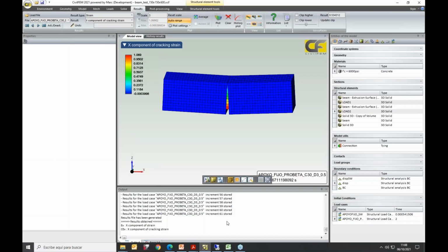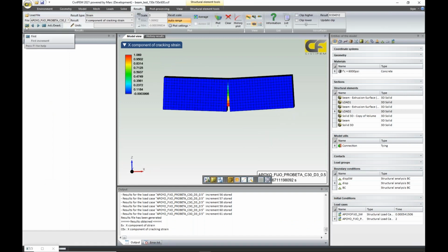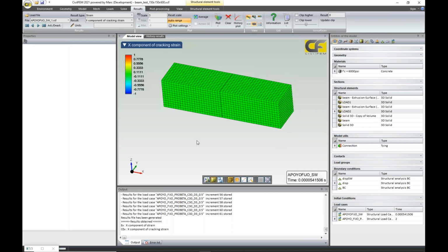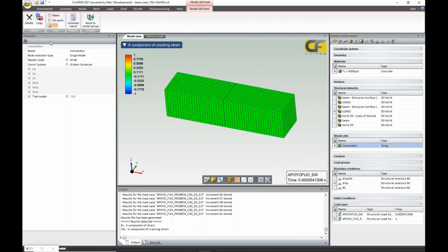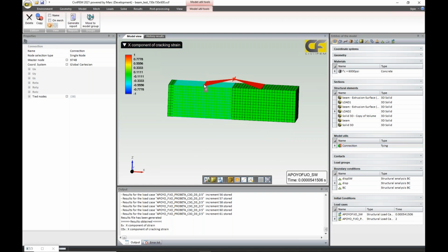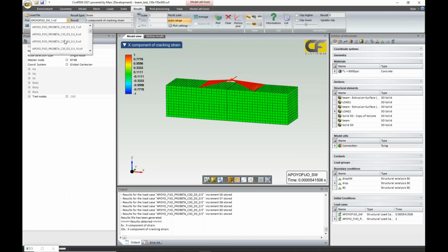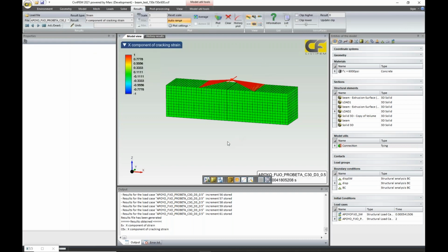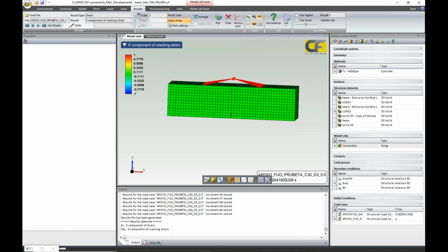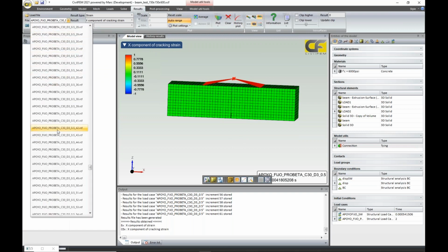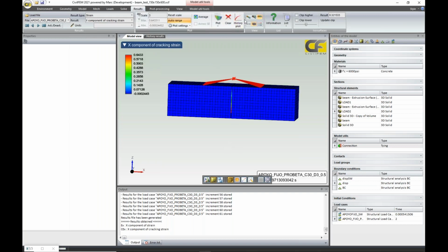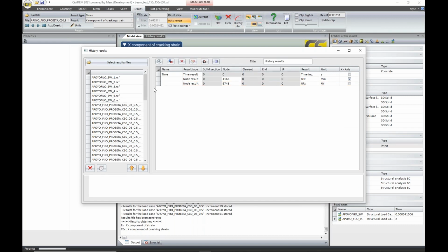So we started with that model. First, in this model we started without any type of deflection. For applying those loads, we just created a node that was rigidly connected to the 2 points where those loads are applied, and applied a displacement there. With the displacement, we could obtain different deflection values, cracking, and an example, this other value where cracking is starting, until the collapse of the model. I'm plotting those results, so we obtain this type of curve.